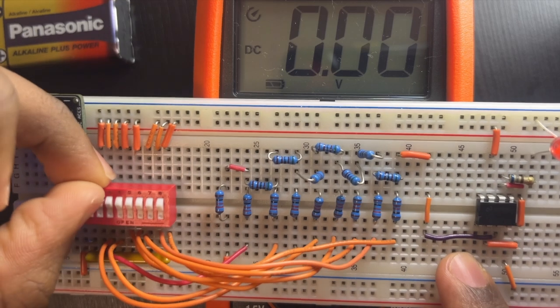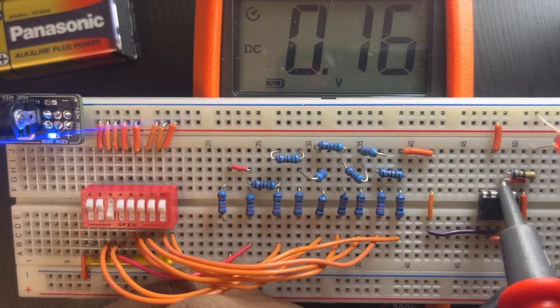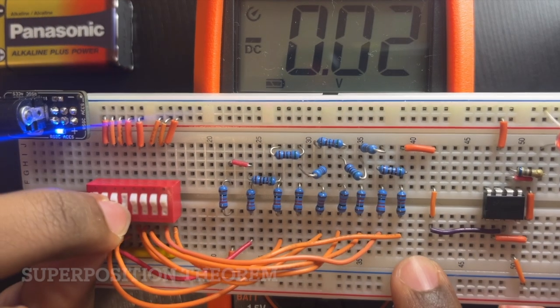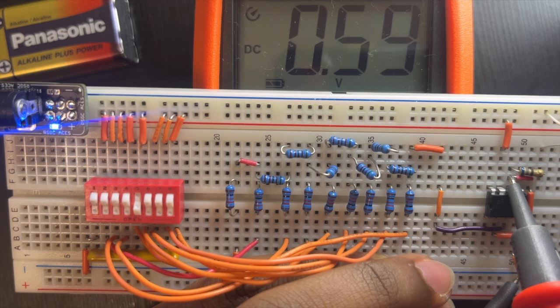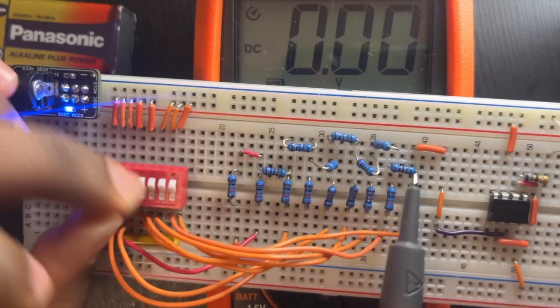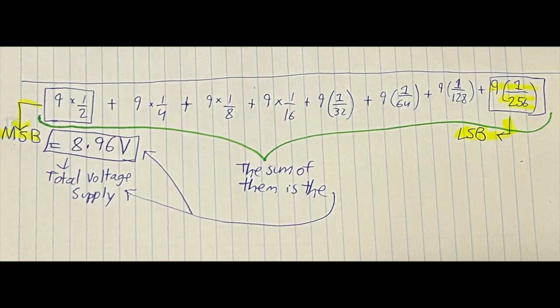We can measure each individual switch's or bit's voltage contribution. This is the application of the superposition theorem. This theory states that in a linear system, the output caused by multiple inputs is equal to the sum of outputs of each of the individual inputs. In addition to the actual measurements that are presented, this calculation can be done to see the approximate voltage contribution of each switch or bit in this case.